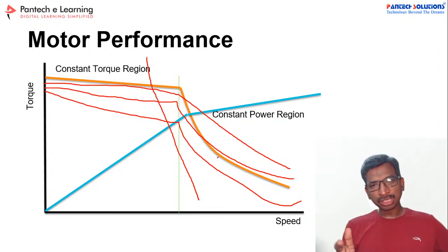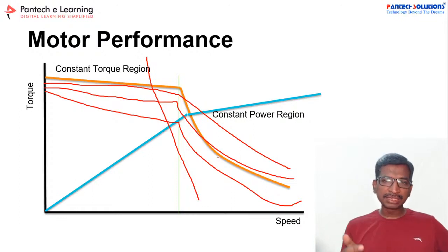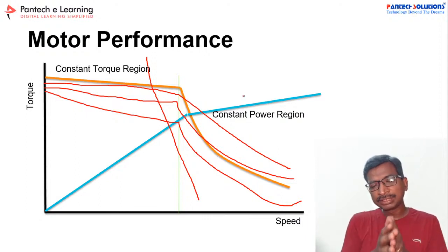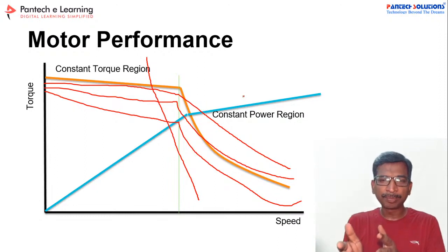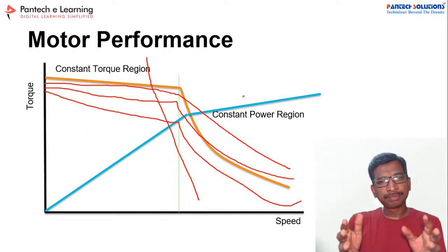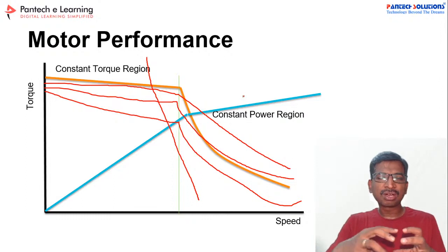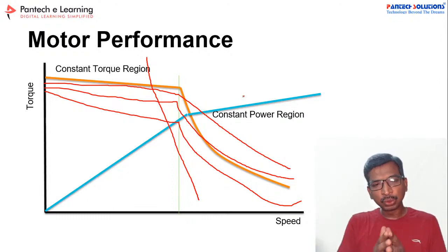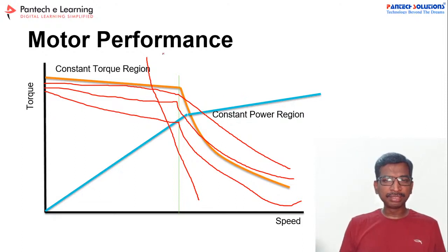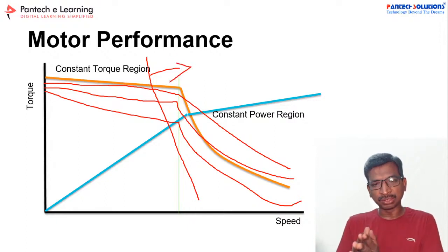Suppose you have chosen a motor at low cost, then you should be able to answer why you have chosen the motor, right? I am going to design my vehicle for a very low speed, like 20 km per hour, and I am expecting a constant speed. I won't drive over a wide range. So I took this motor, this graph, because my aim is to reduce the project cost.